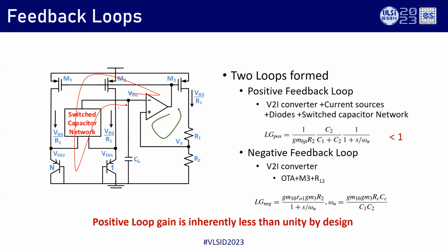First of all, for the BJT, if you dump delta current into this, the voltage across the BJT is delta times 1 by GM, and that is the op amp input. So the current flowing here is delta by GM times 1 by R2. Sorry, my apologies, there is a typo here, this is R2. We corrected it a few slides later, but I forgot here. So VB is delta by GM, and that times 1 over R2.